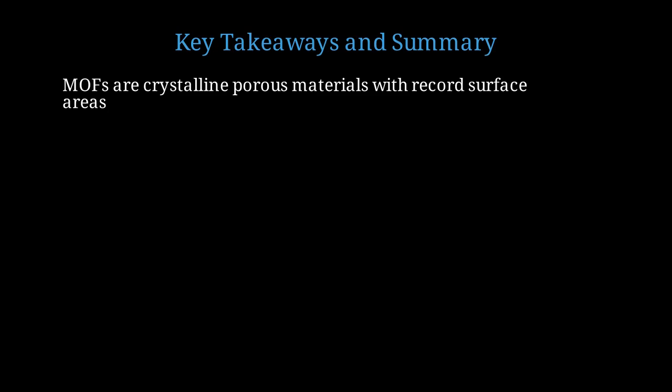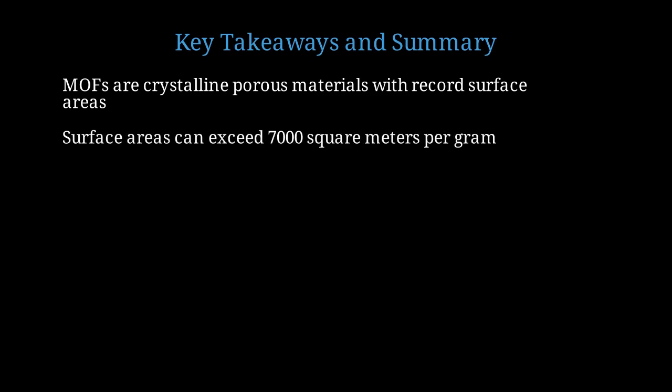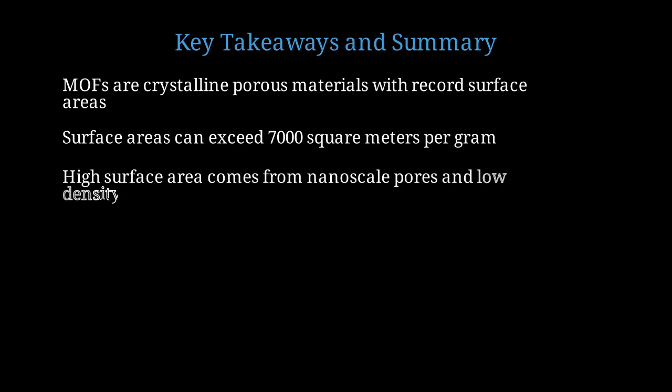Let me summarize the key concepts we've covered about MOFs. MOFs are crystalline porous materials built from metal nodes and organic linkers, achieving record-breaking specific surface areas. The surface areas can exceed 7,000 square meters per gram, equivalent to a football field in just 1 gram. This high surface area results from having nanoscale pores packed into a low-density framework.